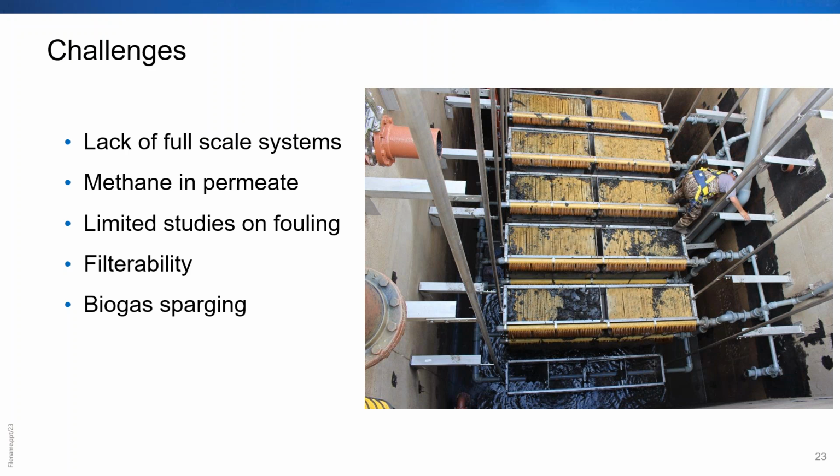There are also very limited studies on the fouling, looking at EPS and SMP relative to how that impacts the fouling and how that's produced in the anaerobic process, and depending on how the SRT or even the feed to the anaerobic process, what is that going to do to those different features that impact fouling? Filterability too is something that personally I've not seen much data on yet, as far as how well anaerobic treatment is filterable by the membrane.